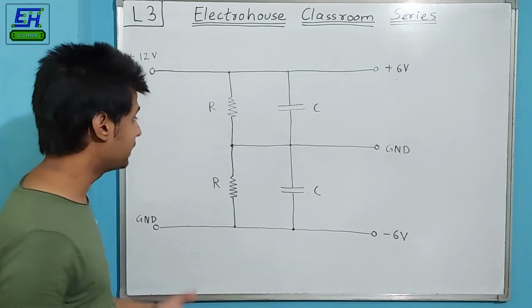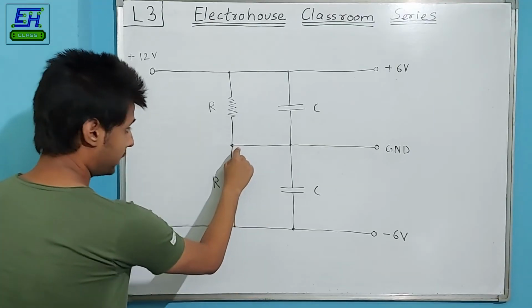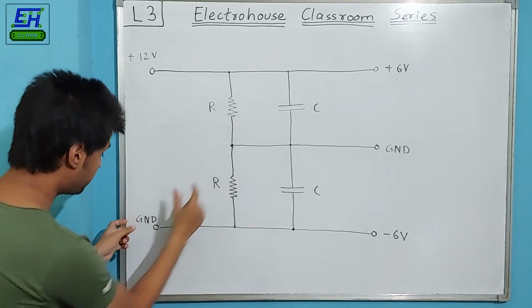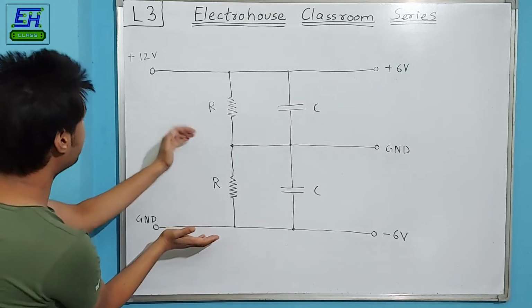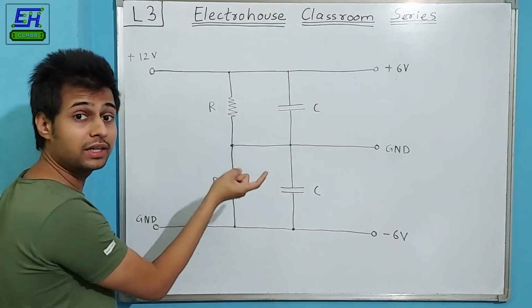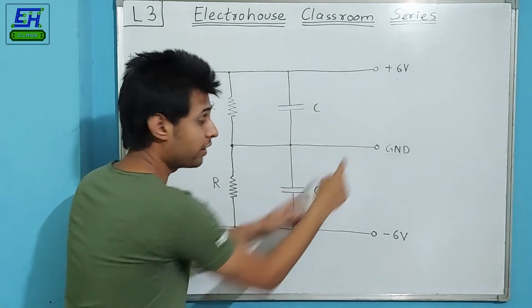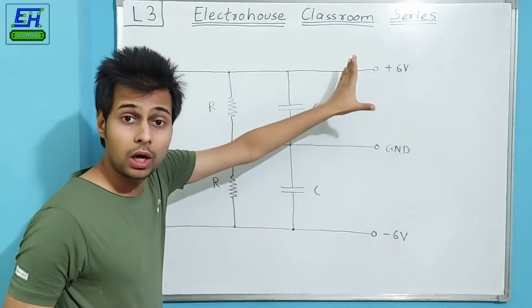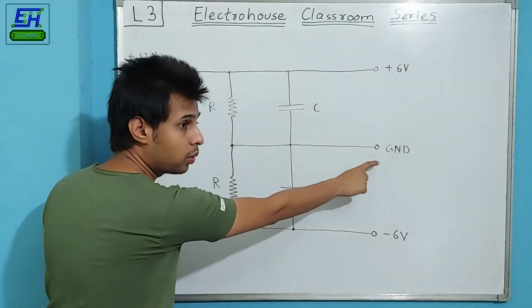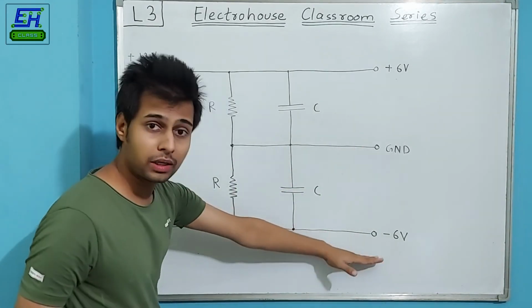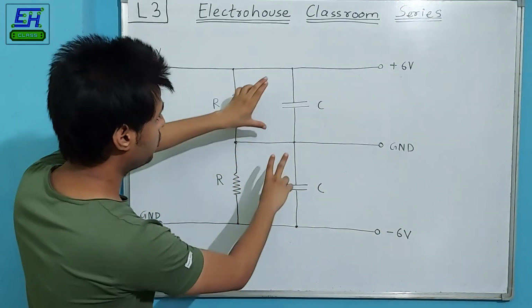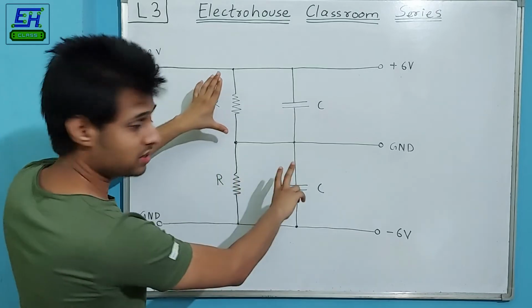But actually in reality, the voltage of this center tap point is half of the original voltage of the input power supply, with respect to the ground. Half of that is basically 6 volts. So here should be 6 volts, but actually we are considering that 6 volts to be our new reference of our new dual power supply. And if you are considering the center tap to be our new ground, so definitely the lower terminal will have a negative polarity.